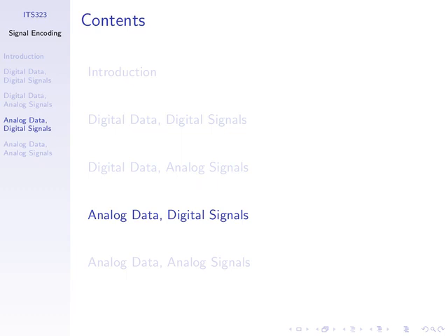So my laptop has digital data, the digital representation of the audio. We had analog in, it converted from analog to digital. So it has digital data. If I want to send that or stream that to another computer wirelessly, I send that digital data as analog signals. That's what we covered at the end yesterday. If we have digital data, we can use things like phase shift keying or amplitude shift keying.